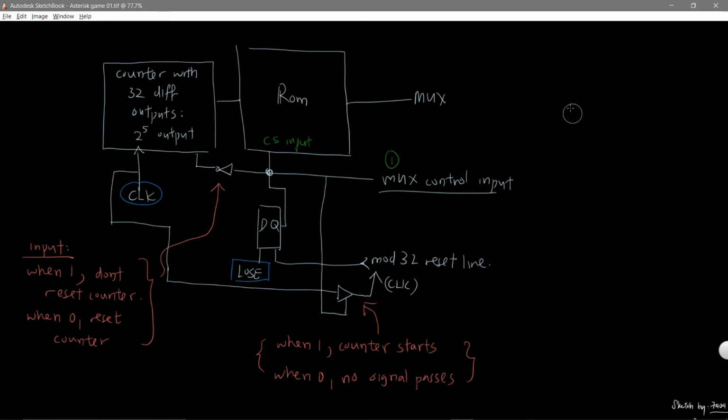And I want to mention a bit of knowledge here. Let's say this is 0 volts, this is 5 volts. A typical FET, field effect transistor, or something like that. Let's say this is 4.5 volts, this is 0.1 volts, depends on the design. And this is called a logic level 0. This is called a logic level 1. And this is indeterminate voltage, from 0.1 to 4.5.